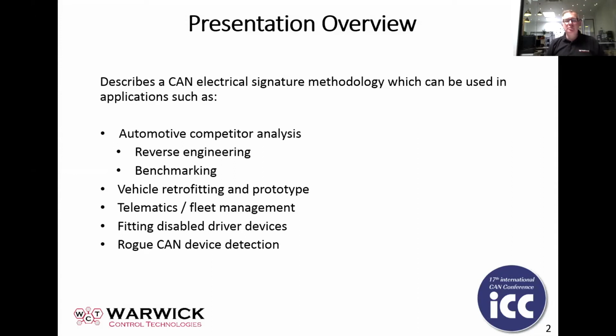Really, what we're talking about today is what we call a CAN electrical signature methodology, which can be used in situations in which you might have to work with a CAN system, but you don't have full information on this system. So these could be things such as, in the automotive environment, you might want to reverse engineer parts of the CAN bus so you can carry out benchmarking exercises.